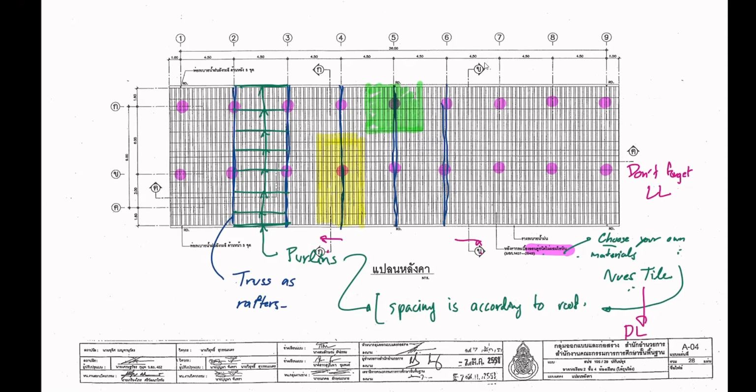There are formulas and considerations available in the AISC design spec if you wish to consider ponding. I myself never look at it, because I always think that the slope recommended by the tiles is good enough. And the way that architects work here, they always use the roof slope recommended by the manufacturer. So you may encounter a problem like that when somebody doesn't follow the recommendations.